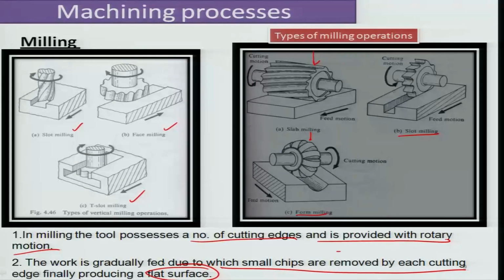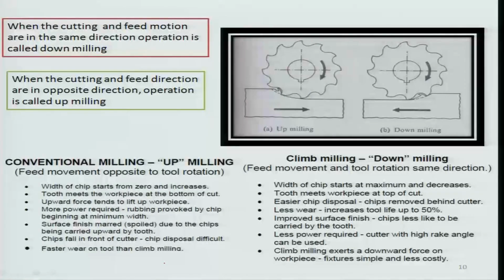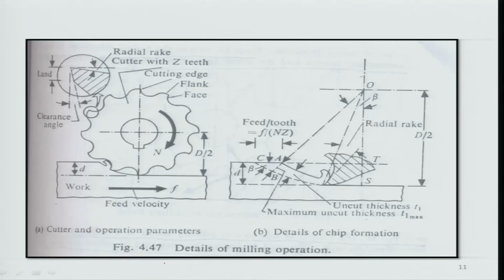Okay. But if I look at the way this milling operation is performed, it is really about that peeling process again, which is happening somewhere here. If the engagement of the cutter happens at a portion somewhere here, there is the original surface which has been cut off into this new secondary surface, and there is a milling chip coming out because of the engagement with the cutter. So, effectively again it is the same peeling process.